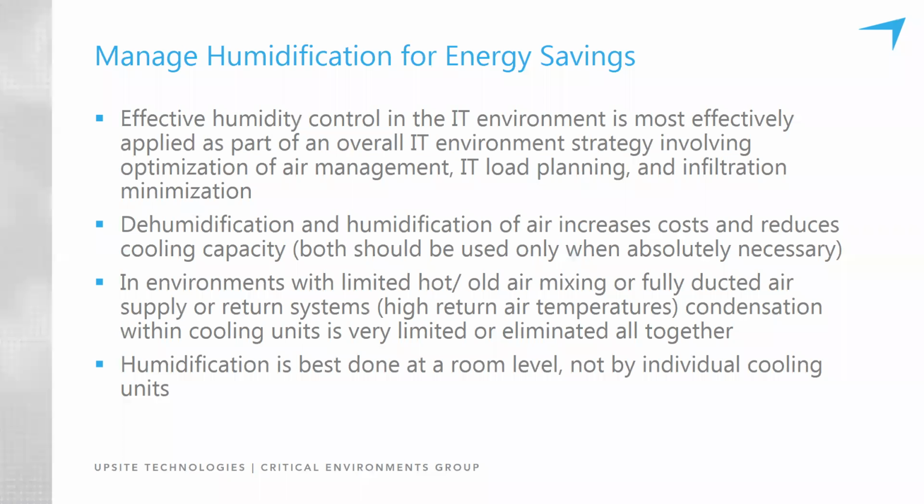Now, as I mentioned, this is a cherry-picked example. Obviously, if you go from 72 degrees Fahrenheit to 74 degrees Fahrenheit return air temperature, it won't be as dramatic because we've already gotten rid of the condensation on the coils. However, there are a lot of facilities that are operating with a small portion or a substantial portion of condensation occurring on their coils. That's consuming a lot of energy and has the adverse effect of also removing moisture, often requiring humidification to get that moisture back into the air. So let's talk about that a moment.